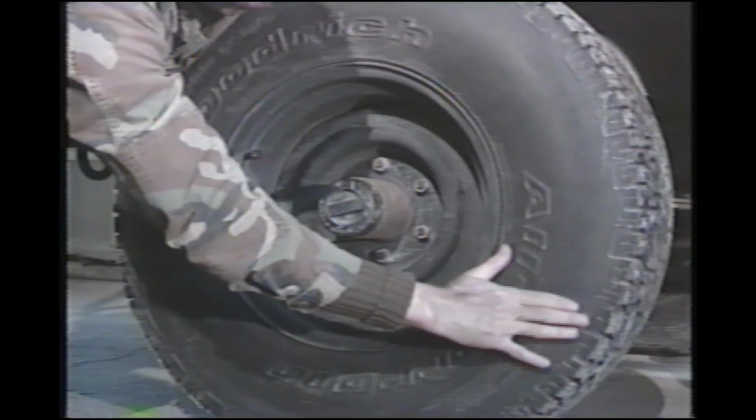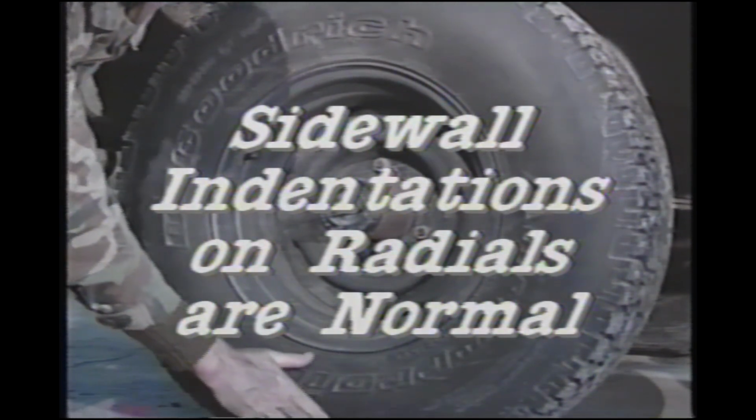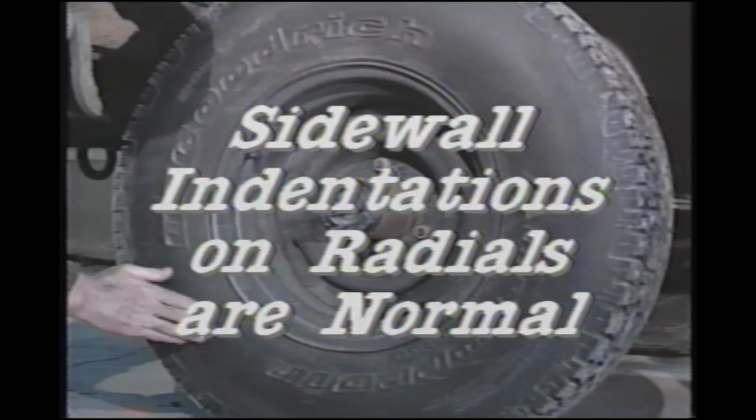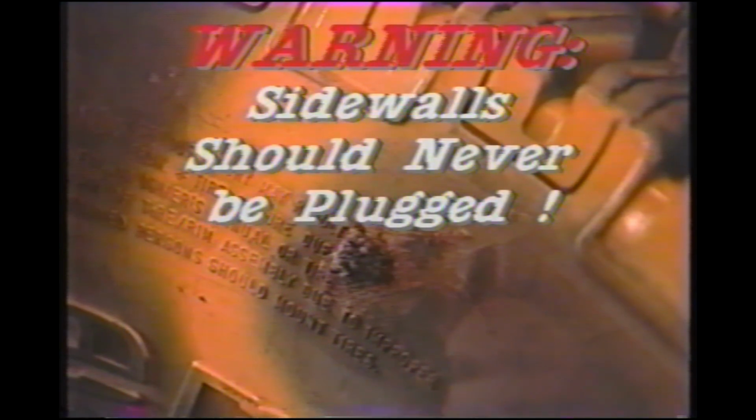Look for body ply separation. Remember, radial tires have indentations. Don't confuse them with separations. Sidewalls should not be repaired with a plug. It may cause an immediate air loss.